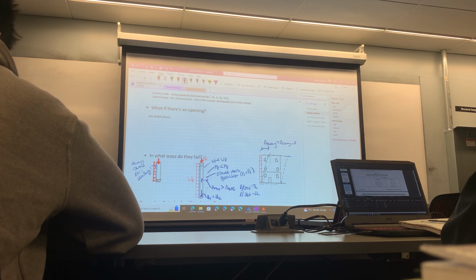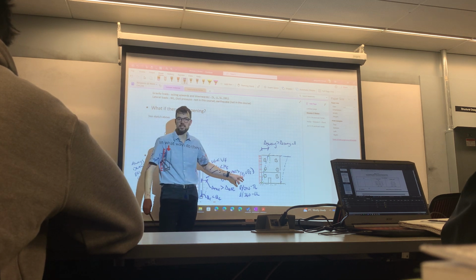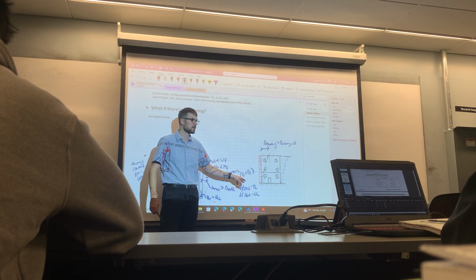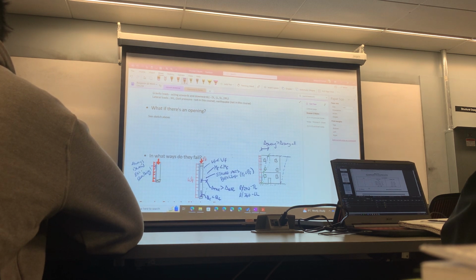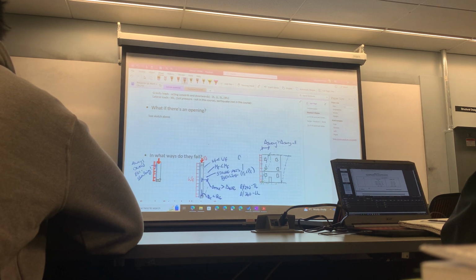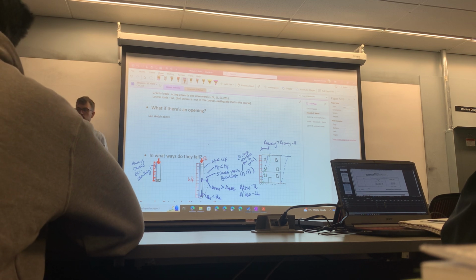Remember, PR includes the buckling tendency and also the compressive resistance parallel to grain. So see how it's the culmination of everything we've done this course?